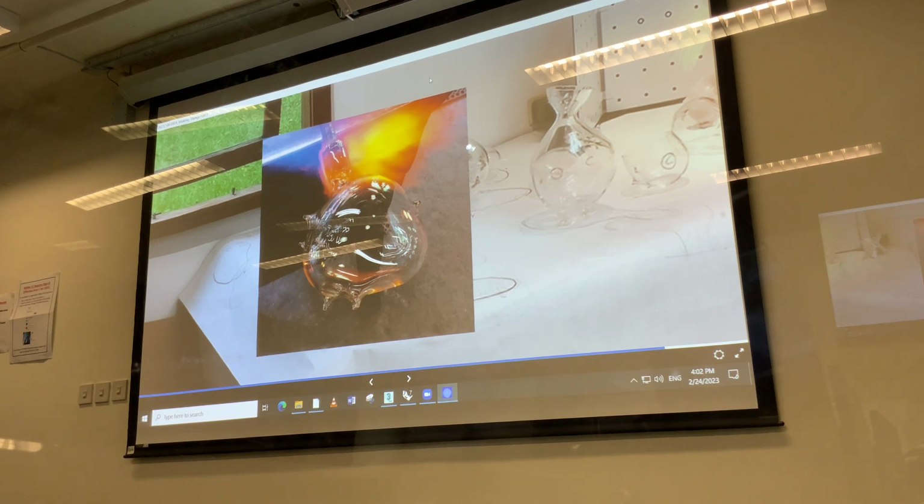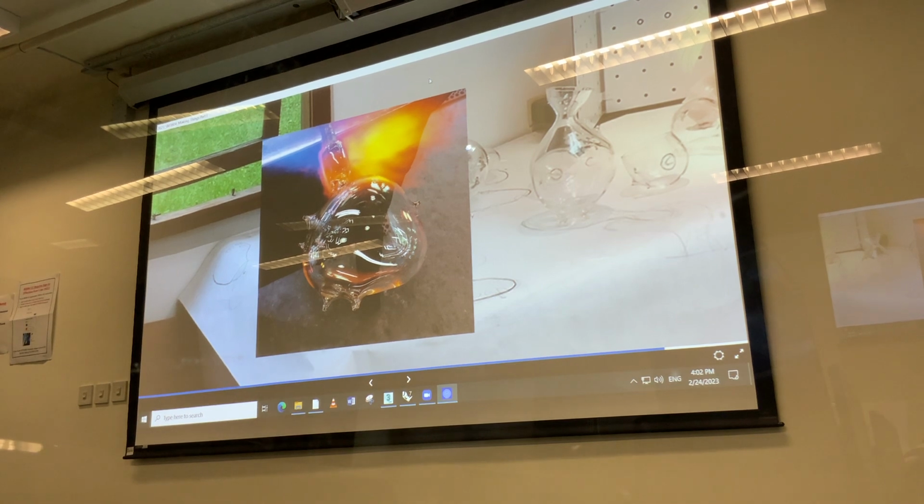And then you heat it up, you inflate it, you make a shape, then it goes into a heating cabinet. You cool down the temperature very slowly, similar to crystal, to not have tension in the glass material. Because if you cool it down too fast, like you can try that at home, take a glass, put it in the oven, and then put cold water on it, the material has too much tension and it would break.